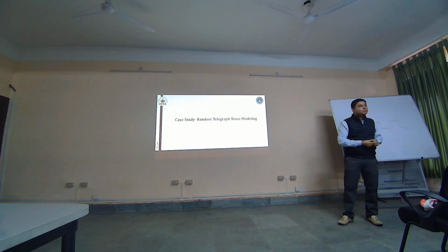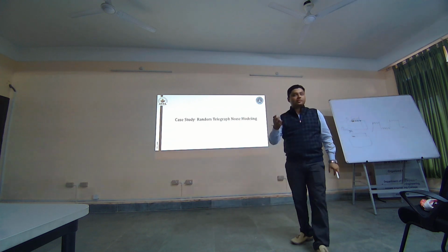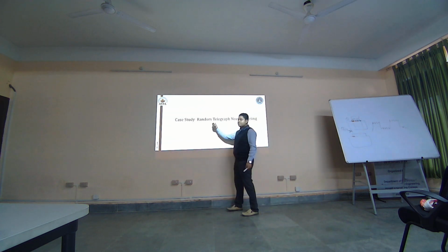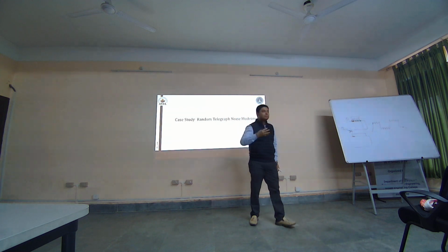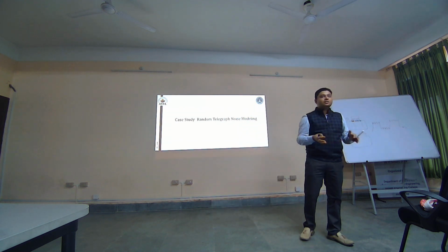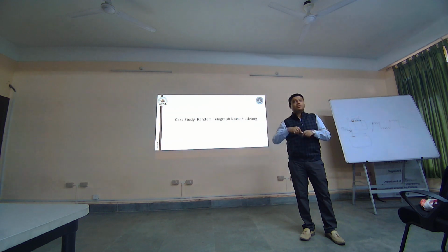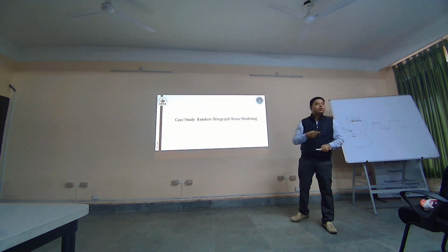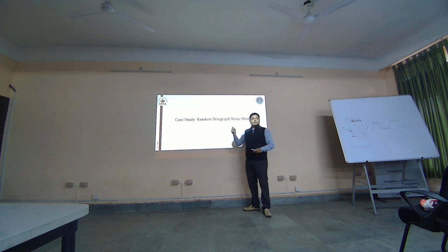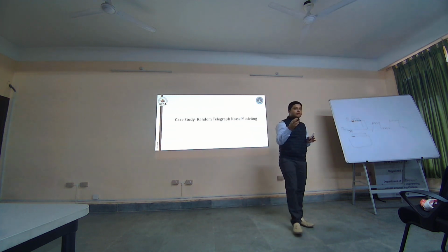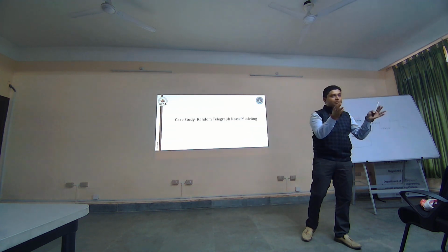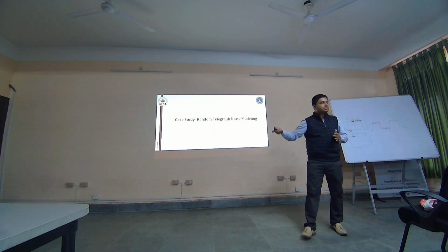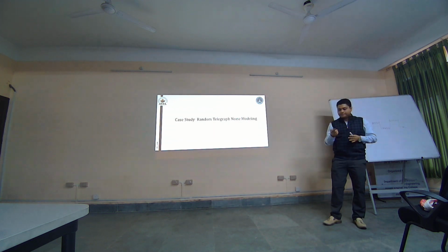Now, the motivation: if you go into an industrial simulator like Sentaurus or Silvaco, you will not find any way to introduce random telegraph noise. You cannot see random telegraph noise as a result in that simulator. You can go up to noise spectral densities, and from there you have to decide that this has this noise, this has that noise, but you cannot actually model it. So what we tried to do was make a model very compatible with the simulation, so that the simulation runs up to a certain point, we extract the data, feed it into our model, and it gives the random telegraph noise. That was the basic idea.